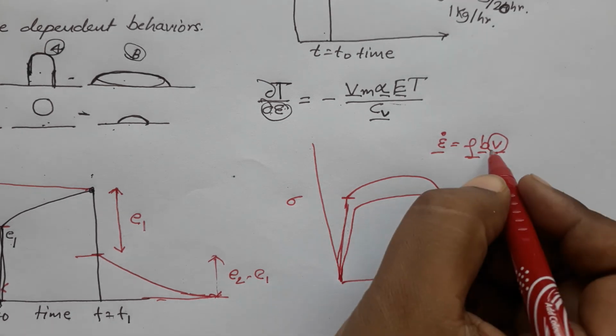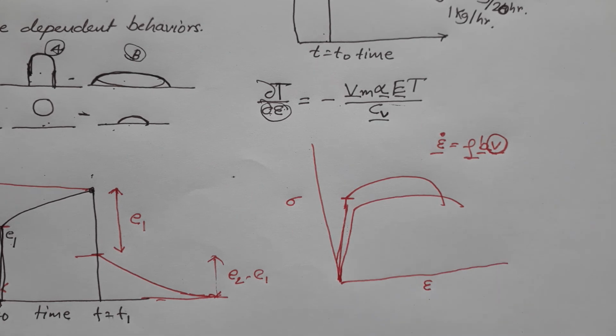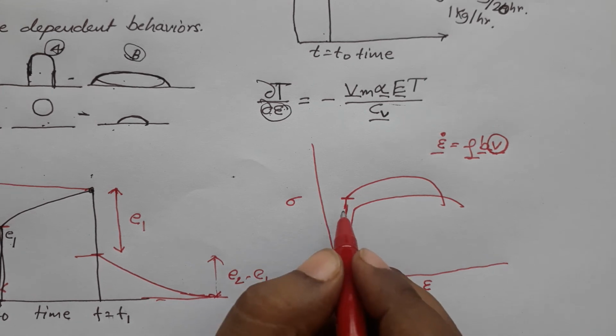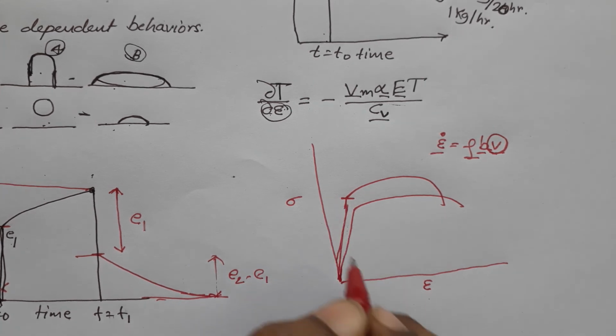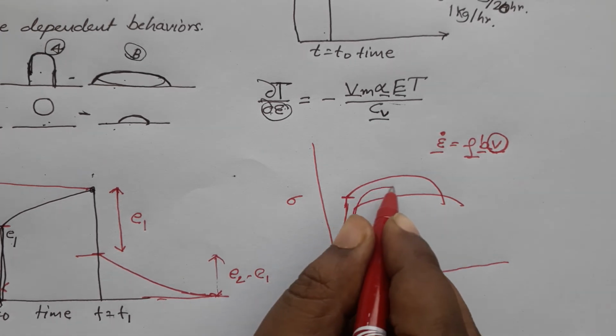What will happen to the dislocation velocity? They should increase. If they do not, then the material will damage and fail, because it is not able to respond to the load you are applying. What we did not discuss in the tensile test was this, that we said that I drew something like this.